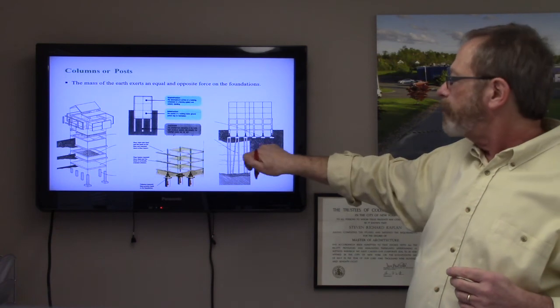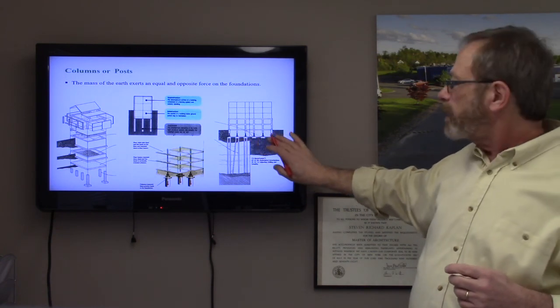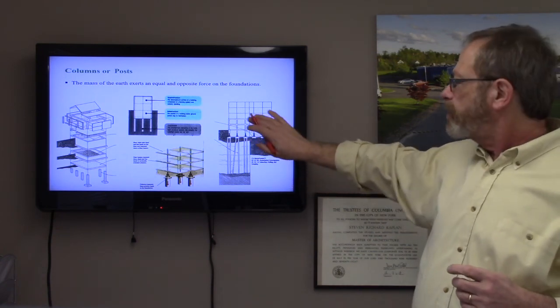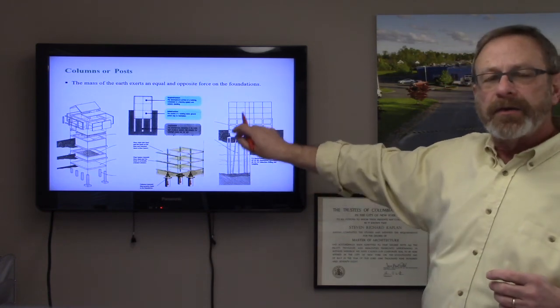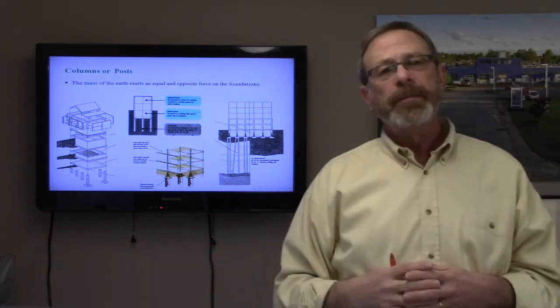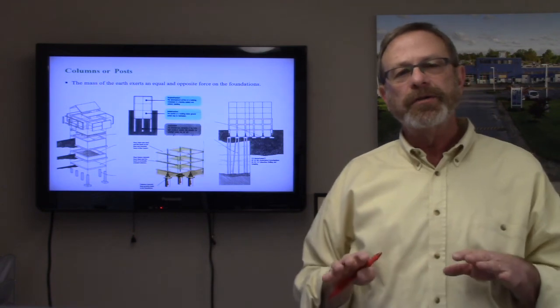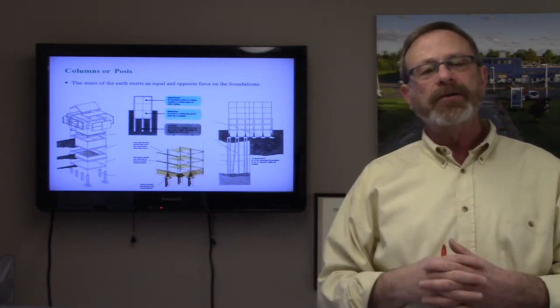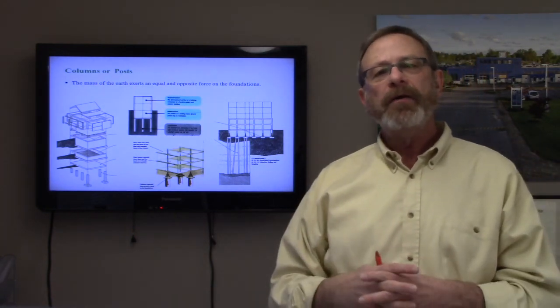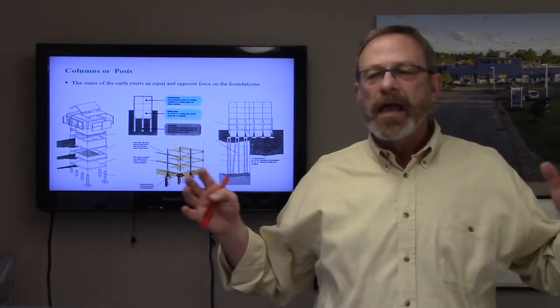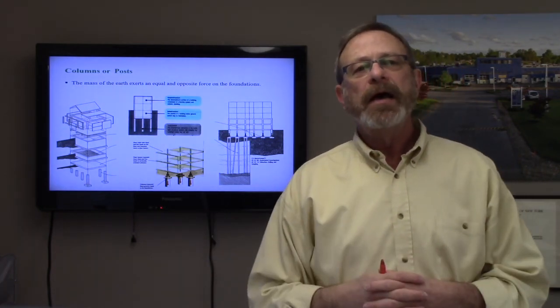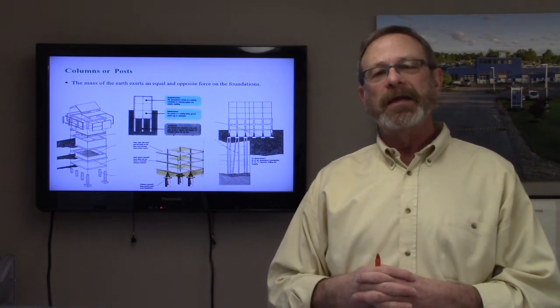And then transferring to foundations, which the soil in this case wasn't satisfactory enough, so they insert piles or casings down to solid bedrock. In Manhattan we look for Manhattan schist. It's bedrock. It's the most compacted earth material that we can have. It goes massively into the ground and pushes massively back up on anything trying to force its way down.